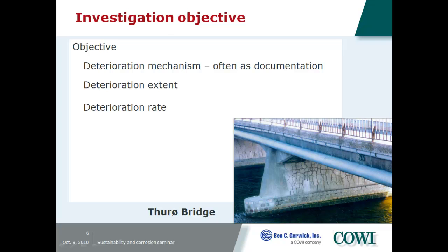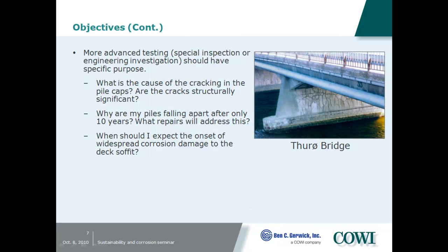Last but not least, the rate at which your deterioration takes place. If it is at such a slow rate, you may want to postpone your repair works. That might be cost optimum for you. More advanced testing should always have specific purposes. What caused the cracking? You can do statistical plans on testing, but very often they would not be economic to perform. So very often it is a selected testing that you do, planning ahead.